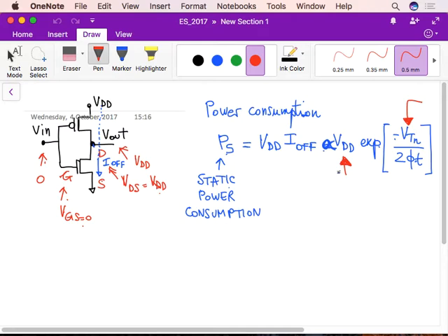Because with CMOS one could say, okay, there is a negligible power consumption in static conditions, because as you know, in the inverter when the output voltage is constant, one of the two transistors is off. So with good approximation, the off current can be considered 0, and therefore, at least with CMOS, you can cut completely off the static power consumption.